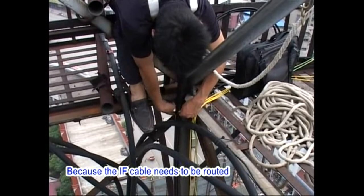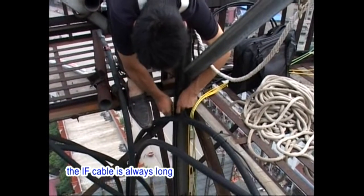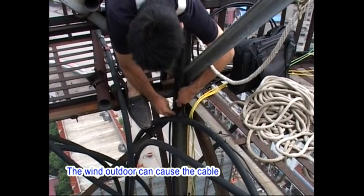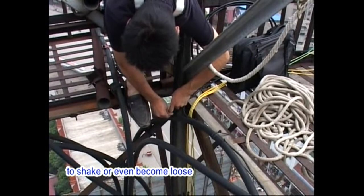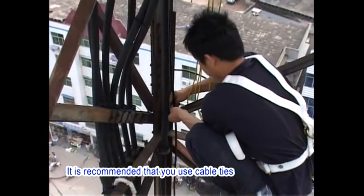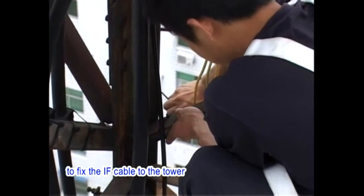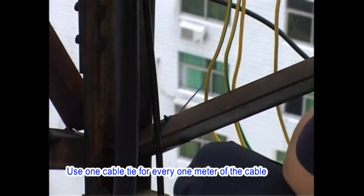2. Because the IF cable needs to be routed from the top of the tower into the equipment room, the IF cable is always long. The wind outdoors can cause the cable to shake or even become loose. Therefore, you need to fix the IF cable properly. It is recommended that you use cable ties to fix the IF cable to the tower. Use 1 cable tie for every 1 meter of the cable.